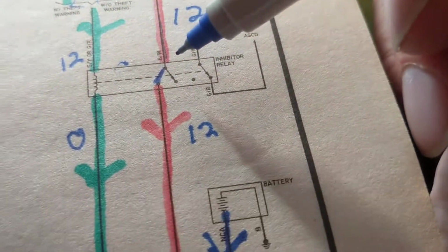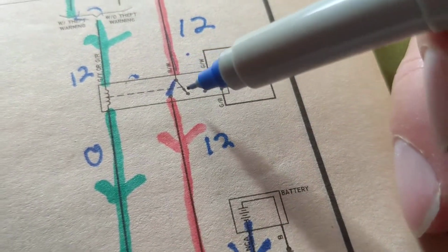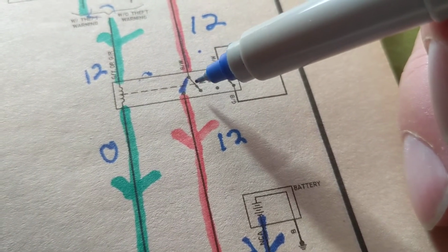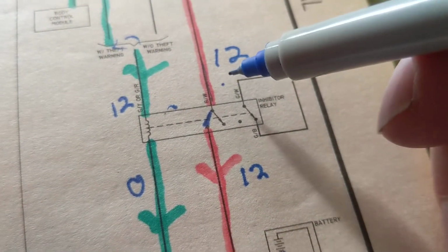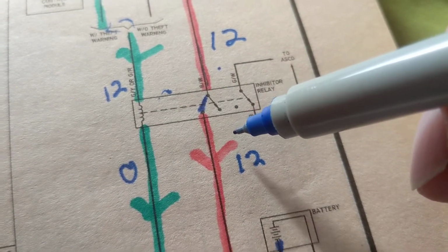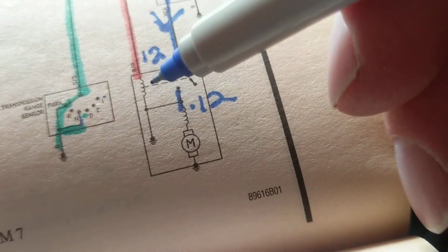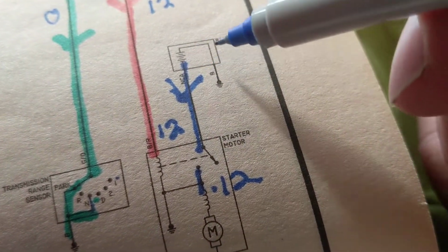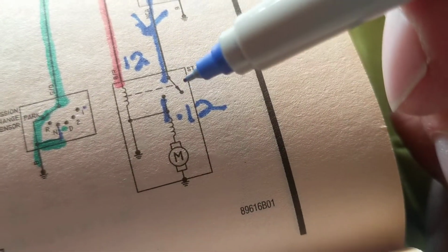They come down here. What about this? I said 12 volts here. Why did I make such a statement? Again, this is just a switch. No resistance. You do not lose voltage drop if there is no resistance, or 0.2 ohms, whatever, which is minimal. Therefore, 12 volts coming in, 12 volts coming out of the switch. So we have the 12 volts needed for this relay to ground. Beautiful. What about this? This is a separate 12 volts. Look at this. Another battery over here, giving it 12 volts.